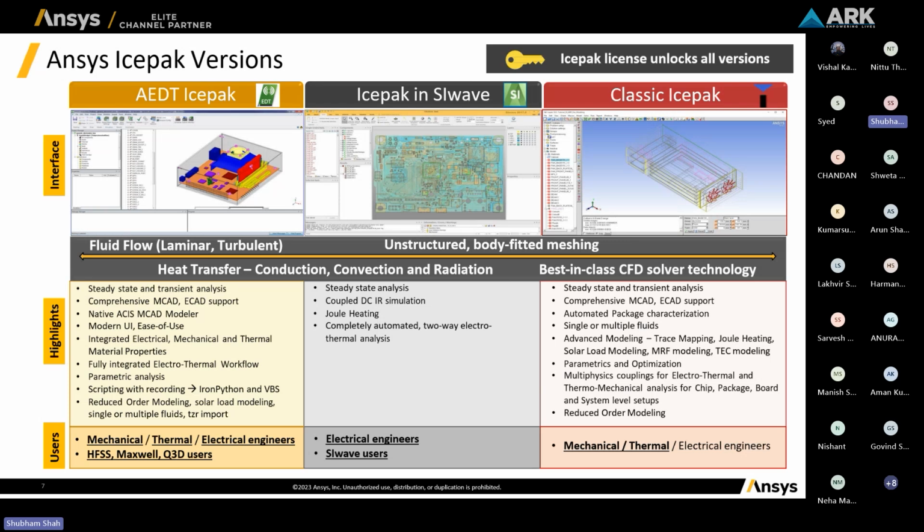Then coming towards MRF modeling. When we model any fan, it's a transient and heavy procedure. For that, there is multiple reference frame modeling. It will give you results similar to running the transient simulation, but MRF is based on steady state modeling. Apart from that, parametrics and optimization is there.